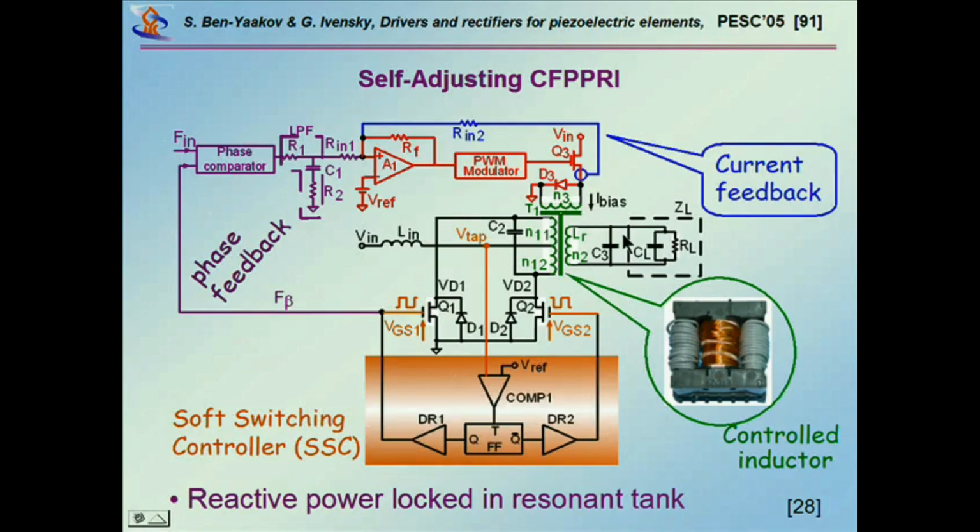And you can now, for example, either change the frequency or change the capacitance. It will also adjust. If you change the capacitance, then immediately this frequency will change because this is locking to the resonance, and now the resonance is different. It will compare to the frequency that you want.